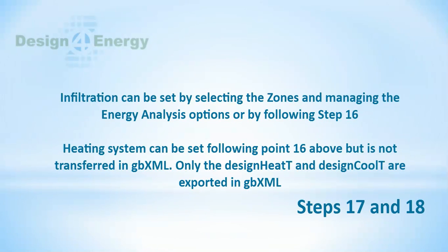Step 17. Infiltration can be set by selecting the zone and managing the energy analysis options or by following point 16 above. Step 18. Heating system can be set by following point 16 above but is not transferred in GBXML.